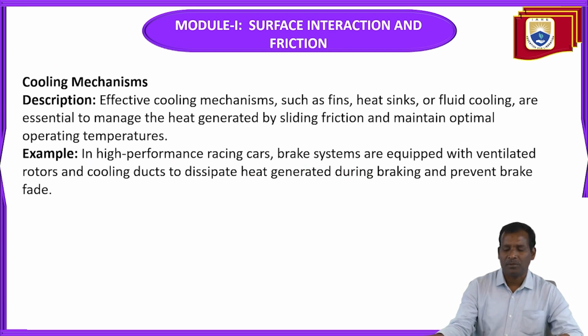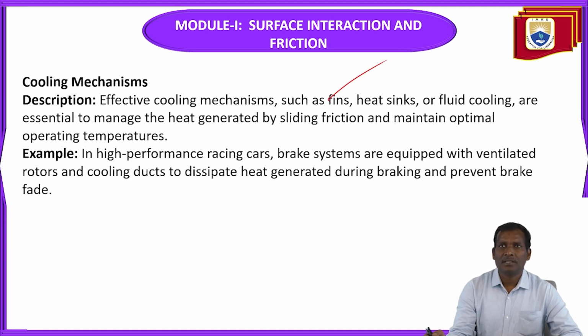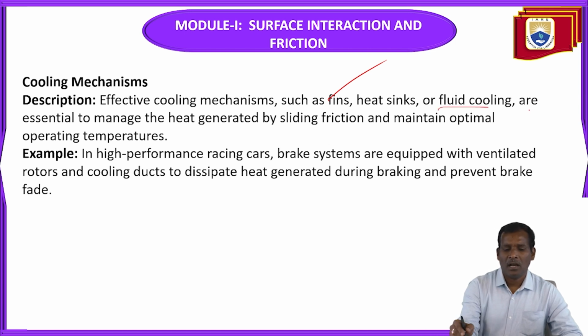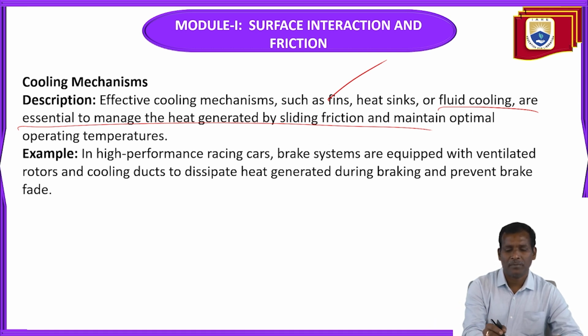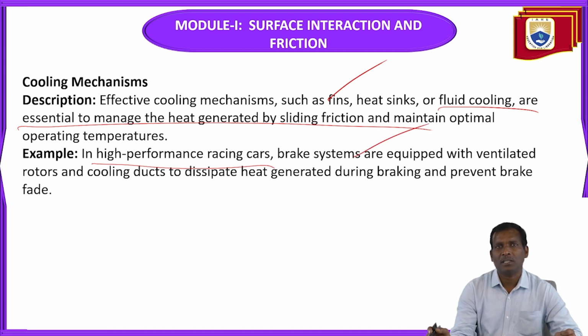Next, cooling mechanism. Effective cooling mechanisms such as fins, heat sinks, and fluid cooling are essential to manage the heat generated by sliding friction and maintain optimal operating temperatures. For example, in high performance racing cars, brake systems are equipped with ventilated rotors and cooling ducts to dissipate heat generated during braking and prevent brake wear.